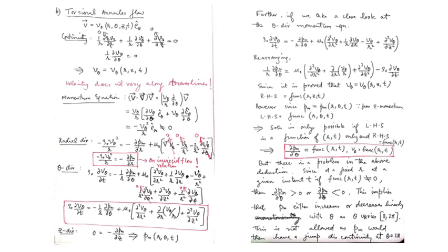So the radial direction equation now will contain this acceleration term, so minus rho naught v theta square by r is equal to minus del p_m del r plus mu naught, and since there is no radial velocity so all the radial velocity terms are 0, and even the v theta term goes to 0 because continuity has shown that v theta is not a function of theta. So all the viscous flow terms in fact vanish. So this is interesting. For a torsional annular flow, when we write the momentum equation in the radial direction, the momentum equation does not contain any viscous force.